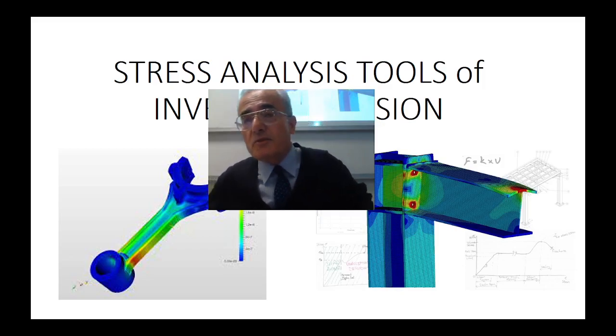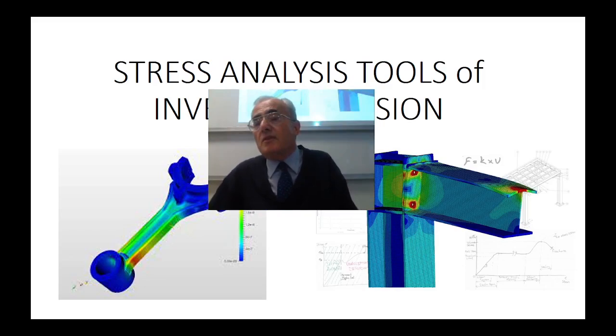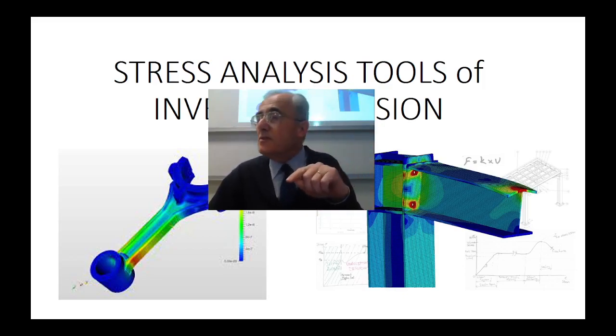If there is a discontinuity, it has also been experimentally verified, there will be stress concentration. If you have such an empty space in the design of the object, in the vicinity of such a discontinuity, use finer mesh, smaller size finite elements.